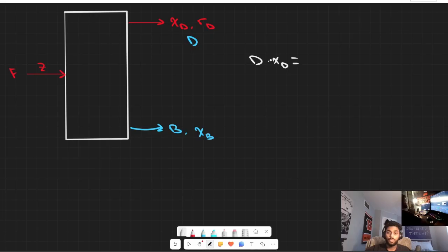We can set this equal to my feed flow rate, multiplied by the composition that I am interested in. But since not all of this is going to show up in our distillate, we account for the recovery that we actually get here at the top, which is a target value.